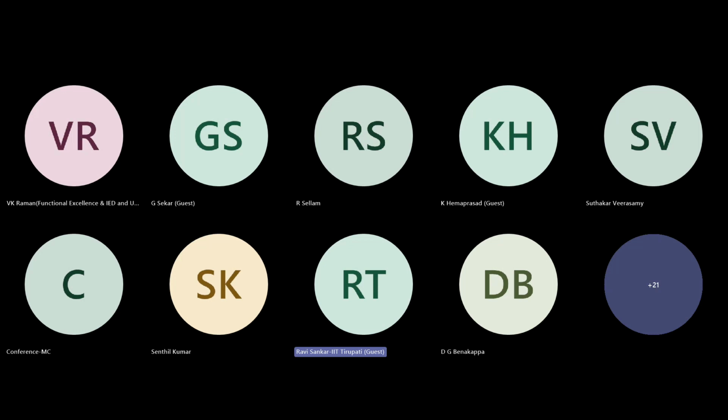The second thing is that you can also go for minimum quantity cutting fluids, where the convective heat transfer coefficient comes in. I think you may be aware of heat transfer and so on. In that circumstance, you can use a minimum quantity cutting fluid. For example, in normal cutting conditions, you will use 400 to 600 ml per minute. That means in the machining region, for 1 minute, the cutting fluid falling from the nozzle is 400 to 600 ml, which is a huge amount.